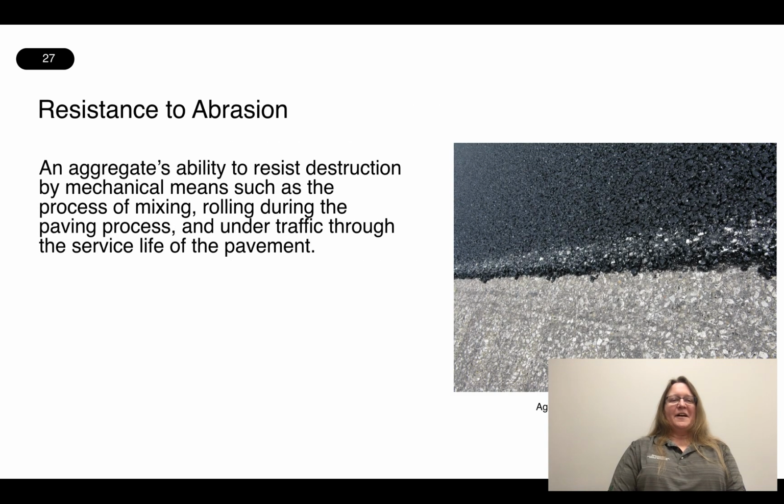So resistance to abrasion is the aggregate's ability to resist destruction by mechanical means, and so rolling during the paving process, and then also when the material is under traffic conditions. So here you can see a picture of aggregate breakage because of the roller.